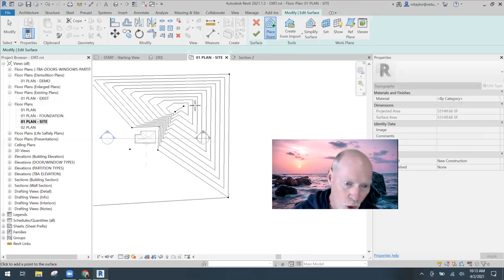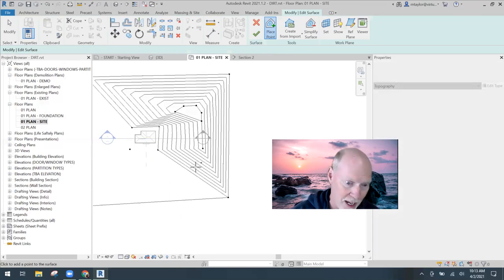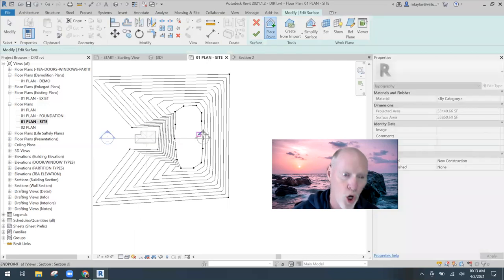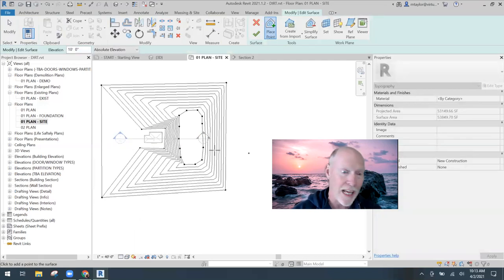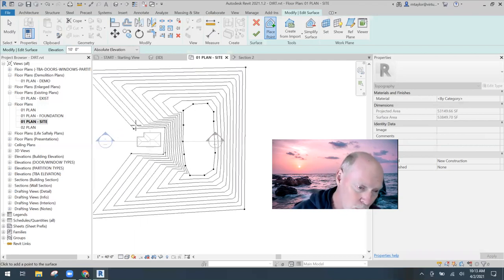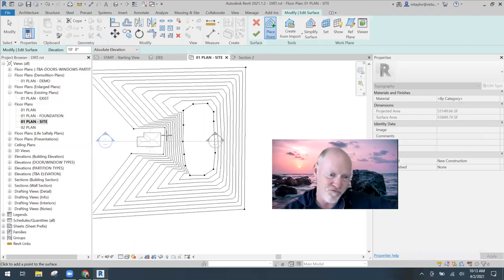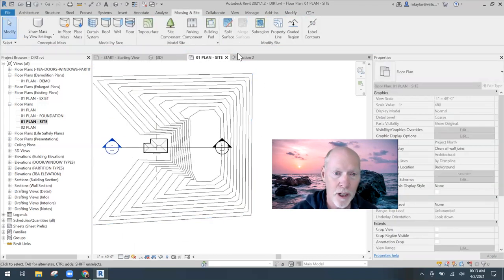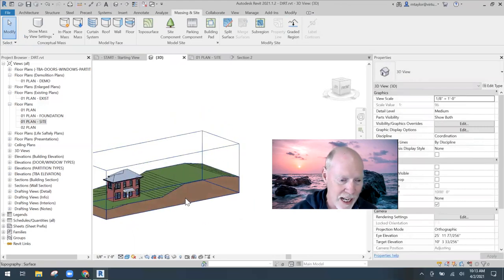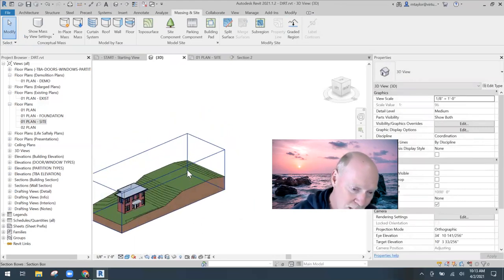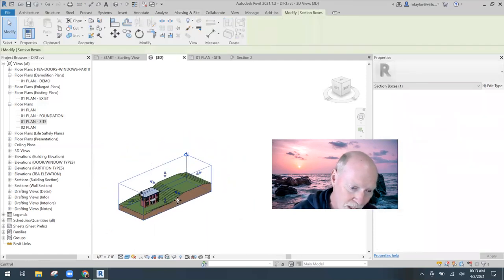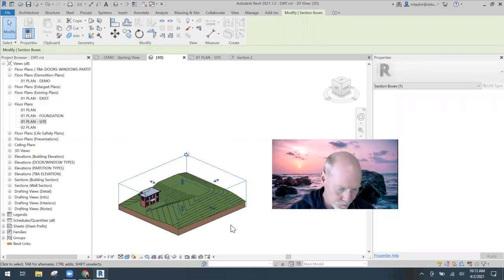And I can click over here, and it just really fast gets, I'm just going to make a round, kind of oval-shaped hill over there. All I did was make myself a little bit of a loop. It held the zeros right around my building so that the dirt didn't fill in, and it sloped up all the way to 10 feet. So if I check the green box, I'm going to go back to 3D. Look, this thing has ramped up into a hill, but I'm intersecting the hill. So if I were to pull this back, you'll see, okay, there's a hill there.